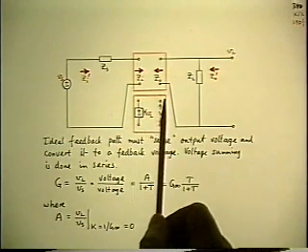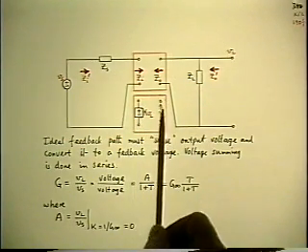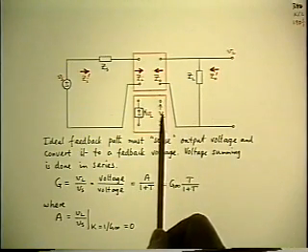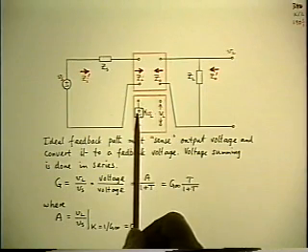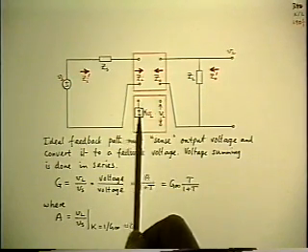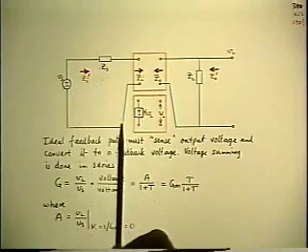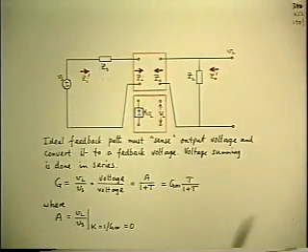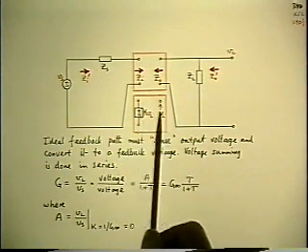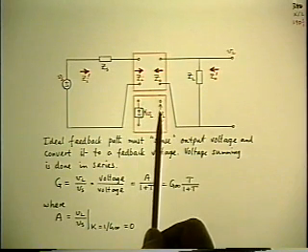That means you're going to have to connect the feedback path so that its input is the output voltage of the forward path, and it has to multiply it by K to produce a fed-back voltage. And the fed-back voltage has to be summed with the input, or actually it has to be differenced with the input in order to get the proper polarity.